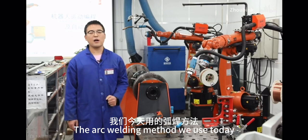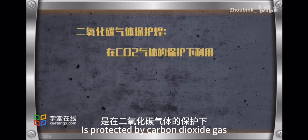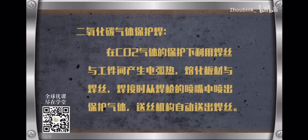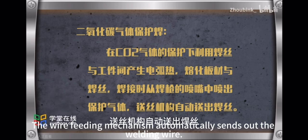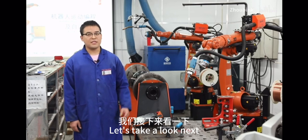The arc welding method we use today is a carbon dioxide gas shielded welding method. It uses the arc generated between the welding wire and the plate to weld, with carbon dioxide gas as the shield. When welding, carbon dioxide gas is ejected from the nozzle as the wire feeding mechanism automatically completes the entire welding process. So how do we achieve automated welding? Let's take a look next.